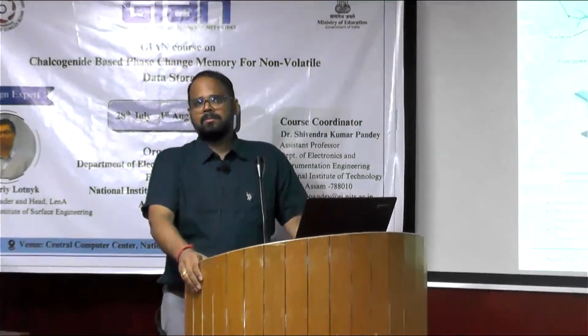No, it is not. See, the first thing is that the technology should be CMOS compatible. We have seen phase change material is CMOS compatible, so that is cross-checked. And we have seen the scaling property is also very good for this material. Now it's your duty to understand the neuromorphic property. You need to check the conductance level, how the conductance is changing, and you need to generate algorithms, like the accumulation property I have mentioned. You can refer to that JAP paper which I have shown. They have systematically designed it, and we have already designed those chips.